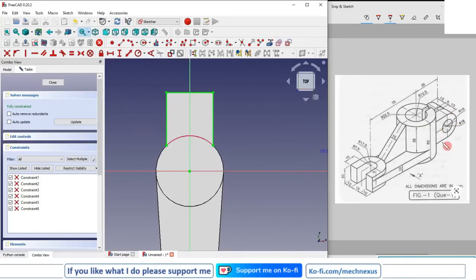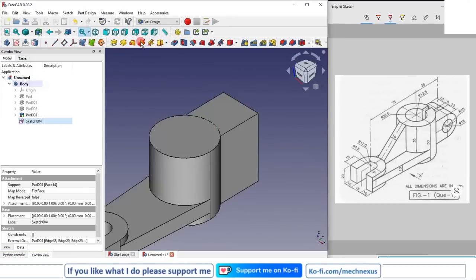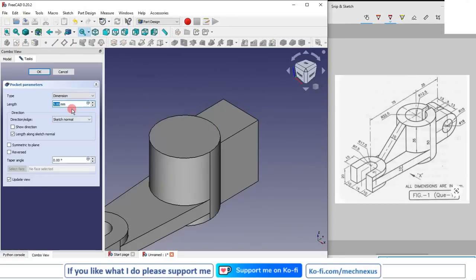You can do it both ways. Either you can take the datum plane and extrude it to 30 mm. Now I will select the 3-point arc. Now I will close it. I will go with a cut, and I will give my cut depth 10 mm.